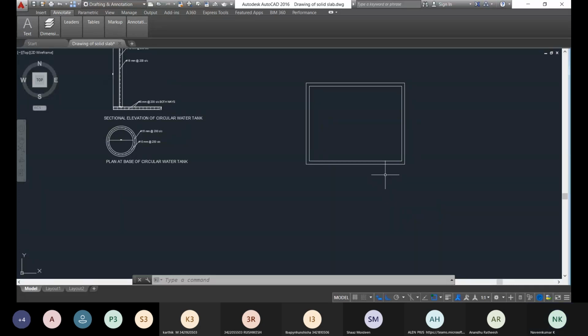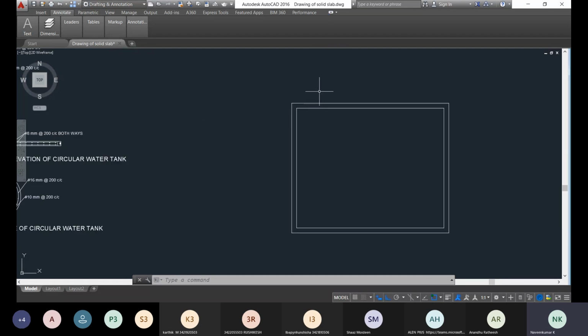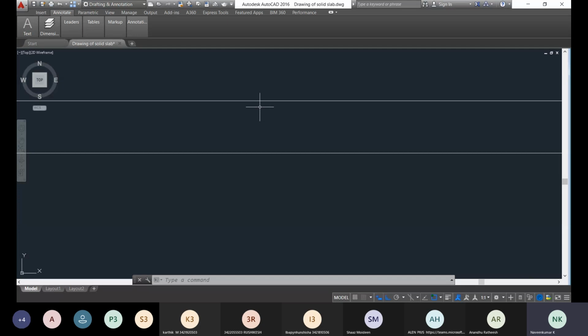Okay, so what is the reinforcement detailing? It is provided in two layers actually. Okay, so the first layer with the clear cover from this end. Okay, so from the top, with this clear cover, the reinforcement detailing are given. Okay, so the overall thickness is actually 170. So with respect to thickness, you offset the main reinforcement detailing and two layer distribution reinforcement detailing.